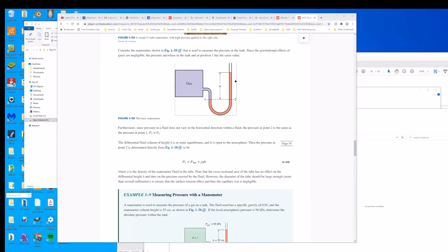Okay. So now this is our change in pressure as a function of depth, right? This is the same type of thing that we looked at previously with the problem with the dam, where the water is forcing down, and you get pressure. It's due to the weight of this column plus whatever pressure is in the atmosphere pushing down on this. You add those two things together to give you the pressure at this point. So the equation essentially becomes our specific gravity times our height, plus the pressure of the atmosphere, which is acting down here. Okay.